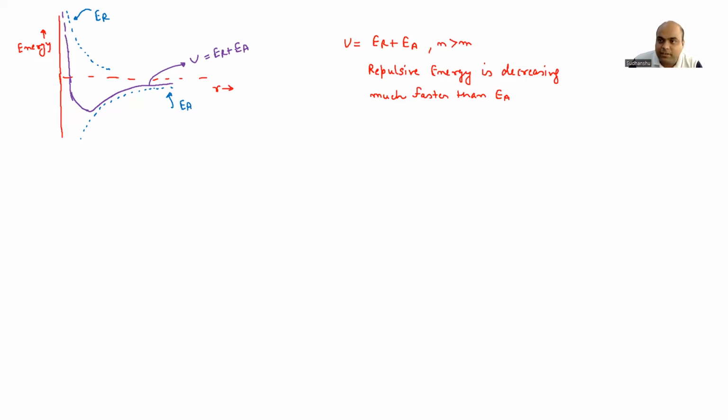Now you can see it is decreasing, it goes to a minimum and then it increases, isn't it? And this particular distance here is your R naught, which is the minimum energy state, that is, the structure is in equilibrium condition. Okay. Now, what is our overall aim? We have to calculate the theoretical strength. That means we have to also know the force, isn't it? And we also know how we can convert energy to force, right? We need to just take the derivative, isn't it? So force is dU by dR.